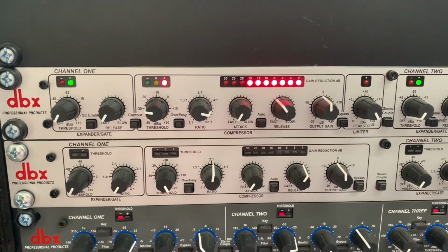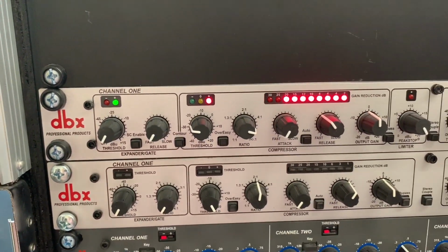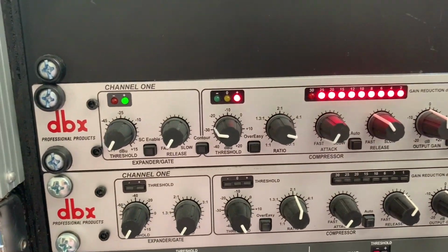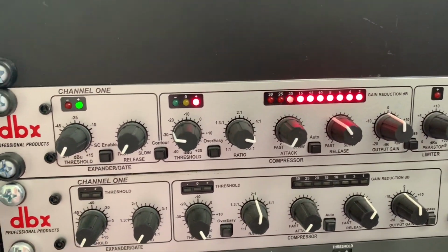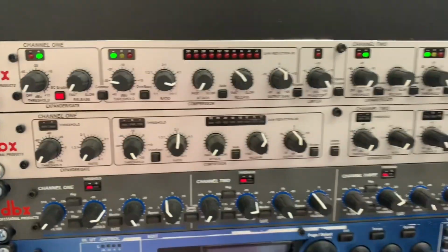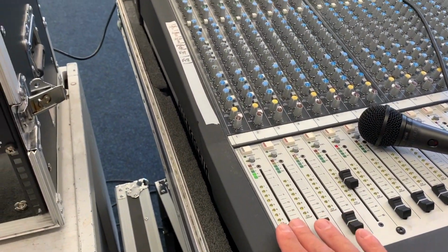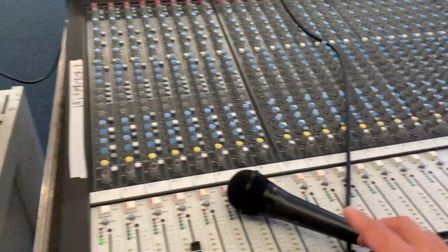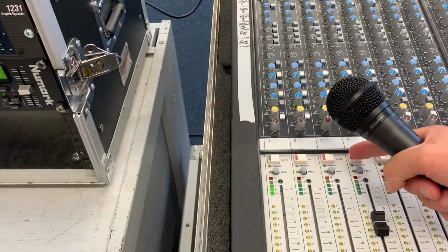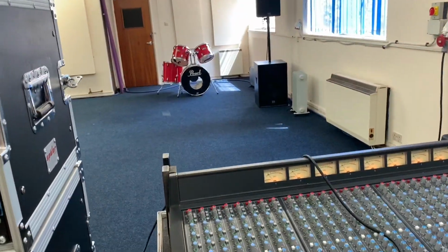Okay, so what I'm then going to do is push this sidechain enable button, because I want the compressor to only work when I talk into that mic, and I've connected a lead into the sidechain at the back, as you saw. So I push that now, the volume's going to shoot up, but I'll then turn it down on the fader. Okay, so now there's my mic, and if I just unmute the channel here, we should hear my voice coming through the PA system up there.